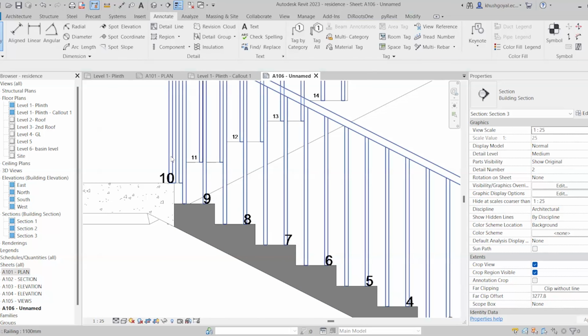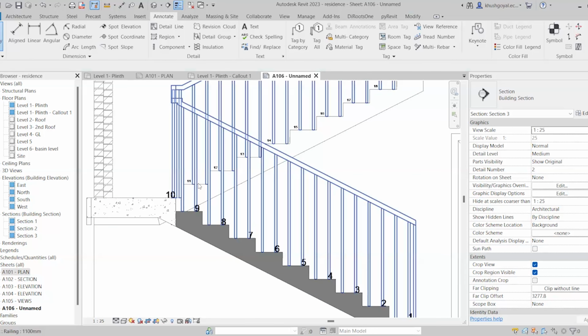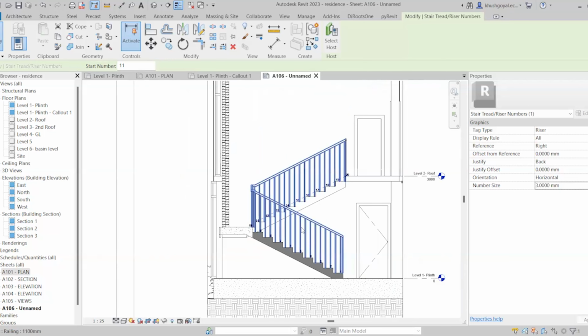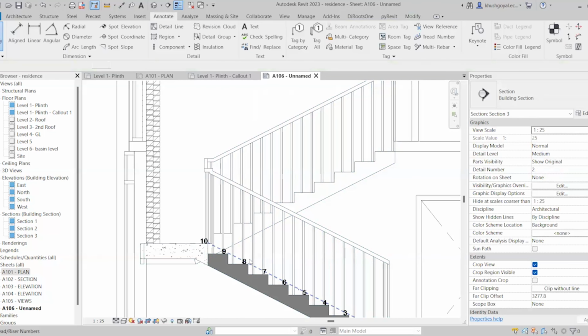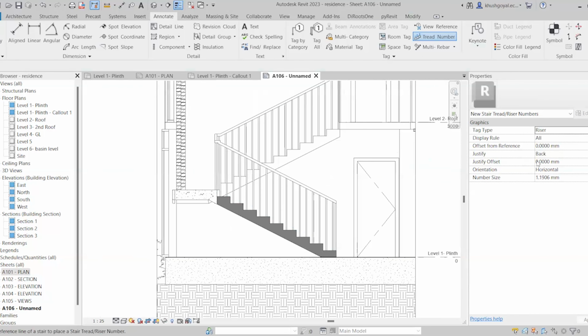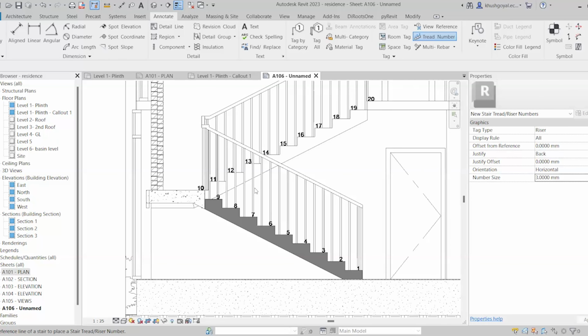Now, if you go to match properties and press MA and okay, you can't do match properties for thread numbering. So you have to select this thread number again, and then give the same property to it. Or what you can do, delete it and I'll show it again. You can just go to thread numbering and before that just make the settings and select it like this. So this is one way of doing thread numbering. But in some cases, we do thread numbering as we have a circle, and in that we put the text. Some cases we do like that.